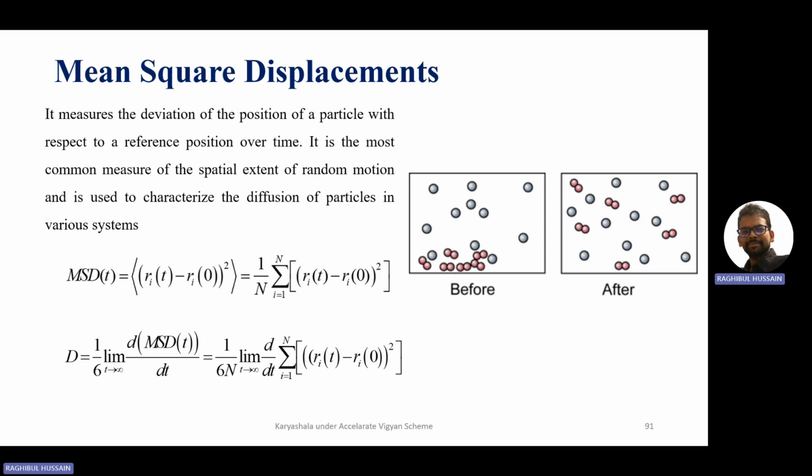And there is a particular correlation to convert the Maxwell-Stefan binary diffusion to the fixed binary diffusion. Okay, so whatever the diffusion we get here, that is the MSD, that means mean square displacement: displacement with respect to its immediate predecessor, squared, and then ensemble average, mean square. If we write it with respect to the discrete formulation, we get this formulation, and the differentiation of the MSD with limit will give me the self-diffusivity.